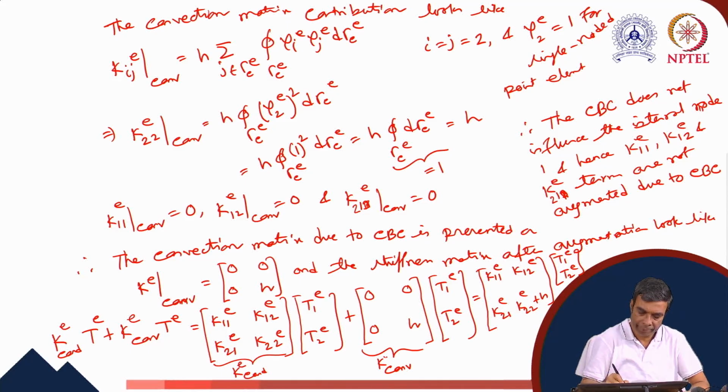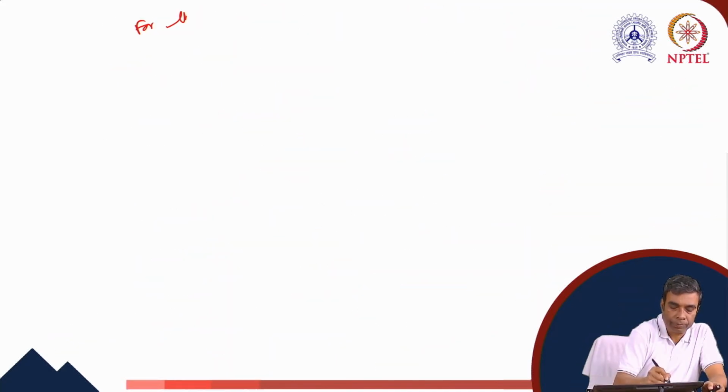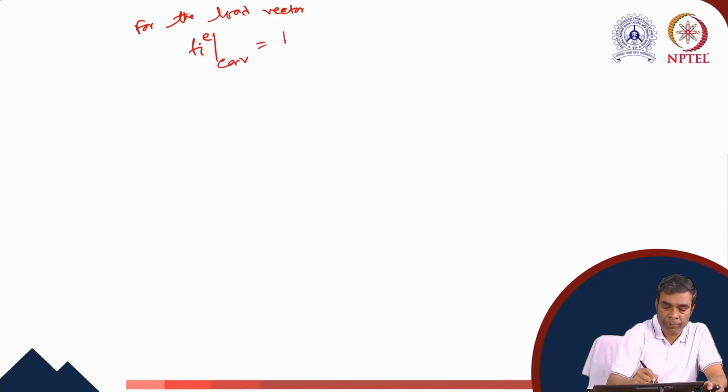For the load vector, FIE due to convection equals h T infinity into integration along gamma CE of psi IE d gamma CE.